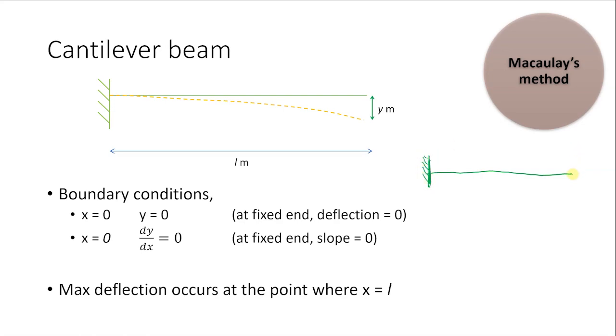The end here is a free end, with no support. Where do you usually see a beam like this? Normally at an awning roof. If you look at an awning installed at a house, above there is your roof, with all the truss and everything. The truss here has nothing, there is no support here. So this is the cantilever beam type.